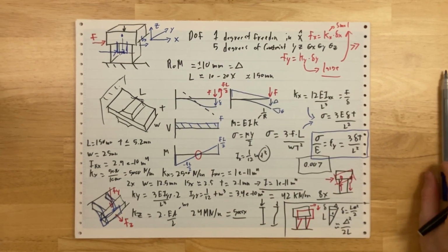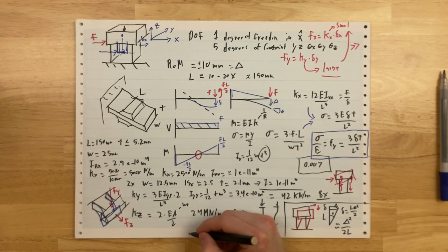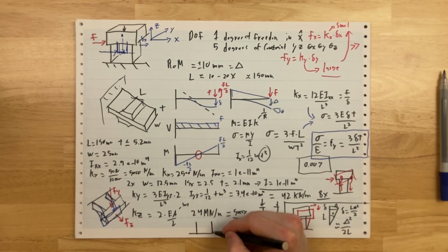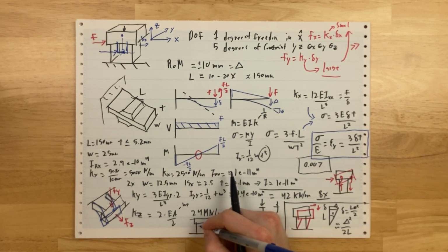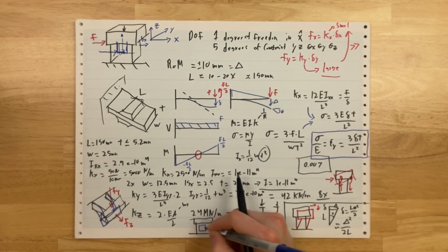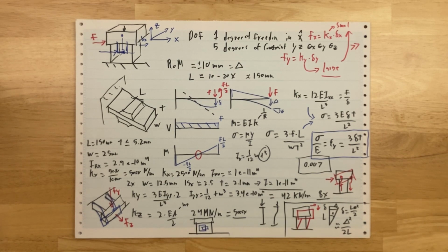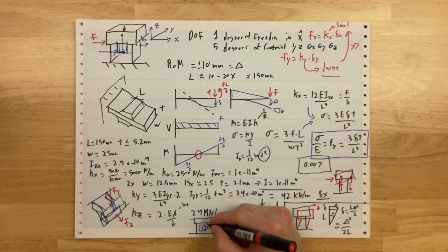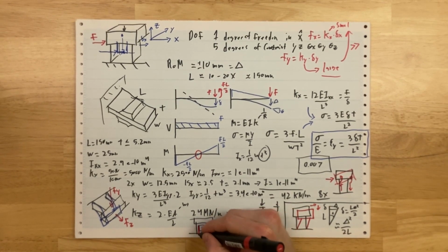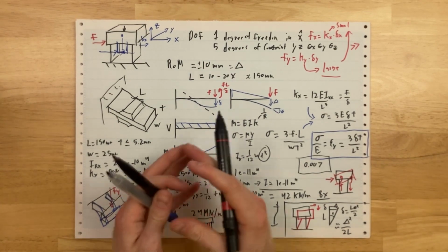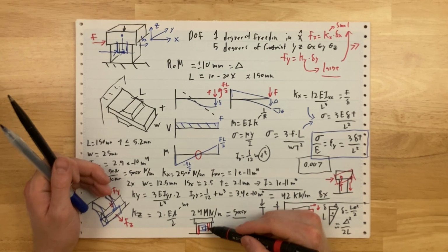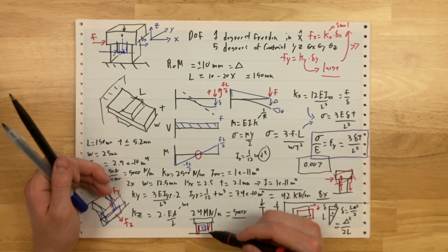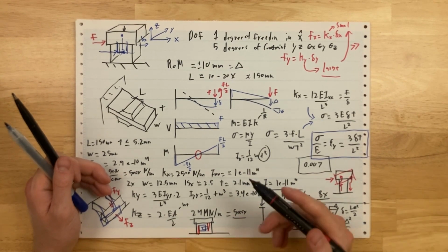And this is actually done in some really good voice coil actuators. You'll find they have a double parallelogram setup, and then they have the voice coil in the middle, and they have these two little beams. One of them reaches up here, one of them reaches down to the base. And basically that voice coil separates apart. The majority of the mass is in the coil, not the bar. And now the center of mass and the center of stiffness are in the same point, and that's the point of actuation. This is a very, very good design.